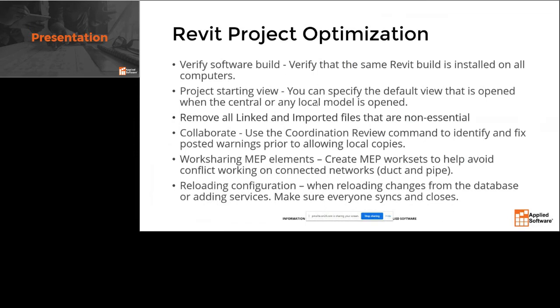A project start view, if it's a simple view, it'll load fast. If you've got it saved to a complicated high resolution image or whatever, it's going to open up a little bit longer. It's going to take longer to open up, right? From a model management standpoint, when we get into the optimization here in a minute in Revit, I'll show you a quick example of something you can do when it comes to a project start view that might help from a project manager's perspective.